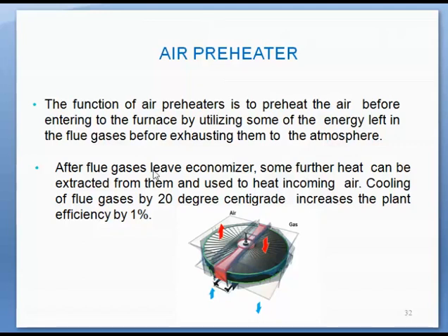The function of the air preheater is to preheat the air before entering the furnace by utilizing some of the energy that is left in the flue gas before exhausting it to the atmosphere through the stack. So you can see in this figure that hot flue gas is coming.